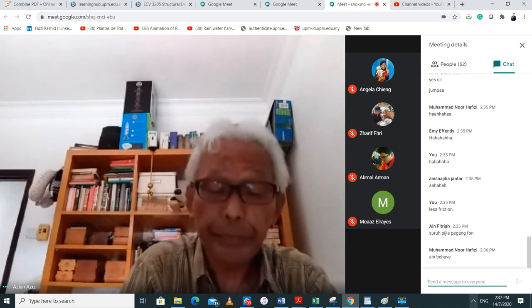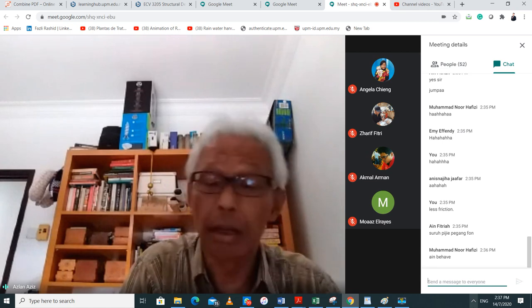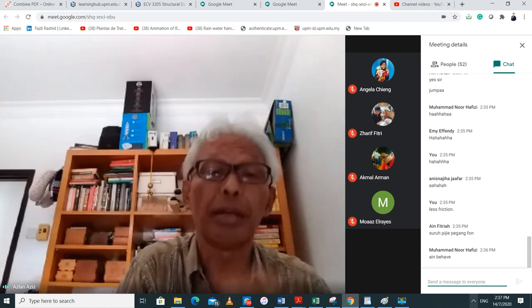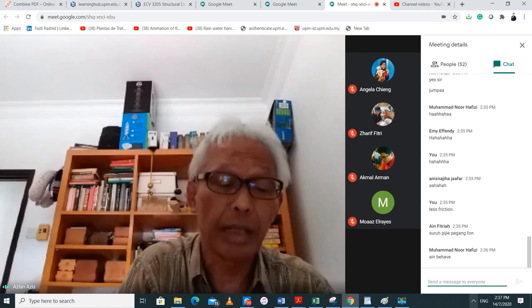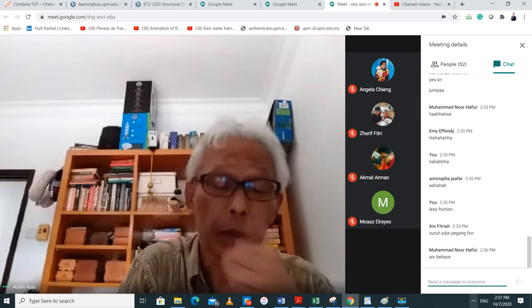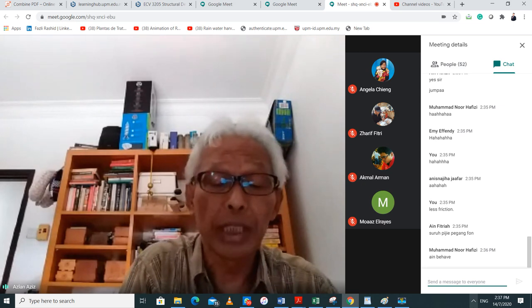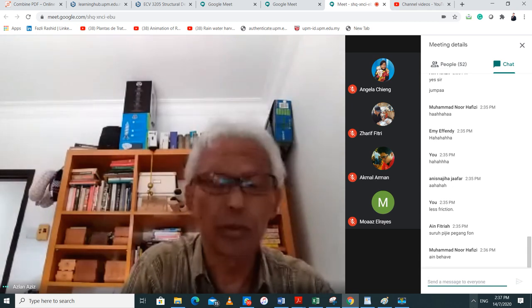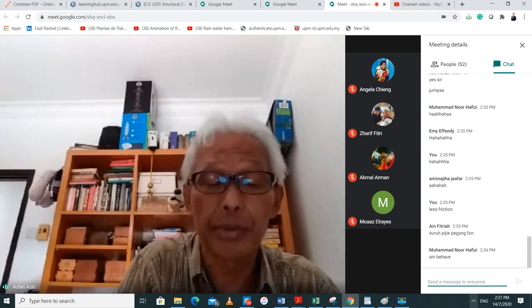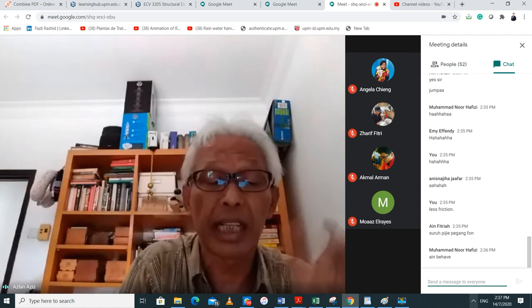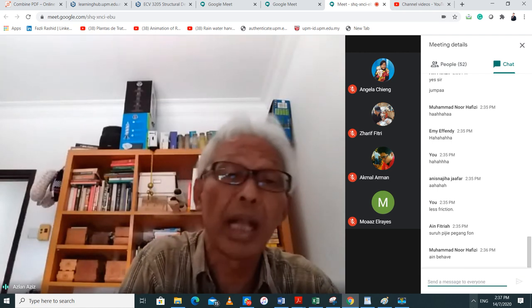Now, if you look at that figure 8.25 on page 349, you have q sub c against depth, cone penetration against depth. Now, you notice that there are two types of soil here. They actually explain to you that there are two types of soil. The upper layer is a loose uniform sand. The second layer is a dense, well-graded sand.